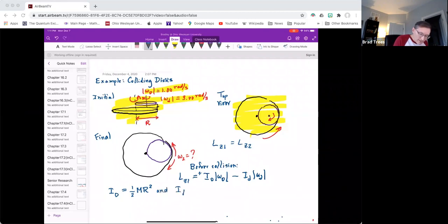Now I little d, the rotational inertia for the axis through the center of the smaller disk, well, it's still a disk. So 1/2 mass, I'm told the two disks have the same mass, times the radius squared. Now the little disk's radius is big R over 2. So I need big R over 2 squared. So what is this? That's m times r squared. 2 squared is 4. 4 times 2 is 8. Looks like that's m r squared over 8.